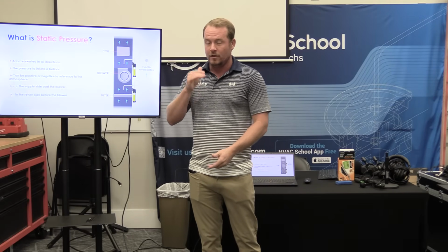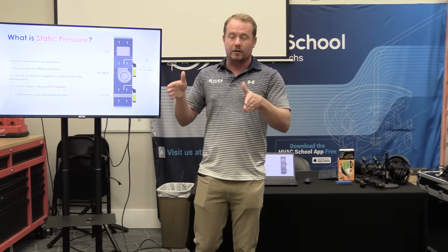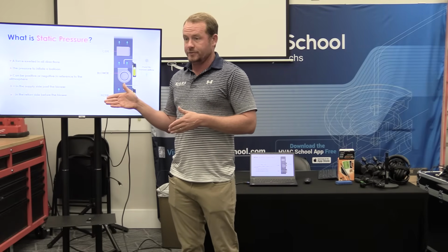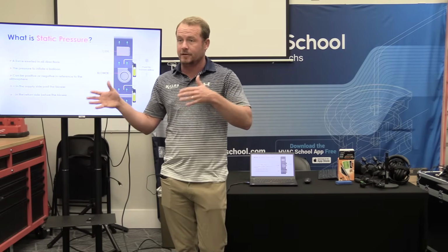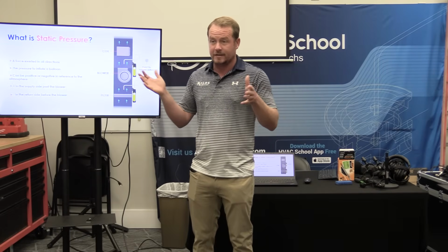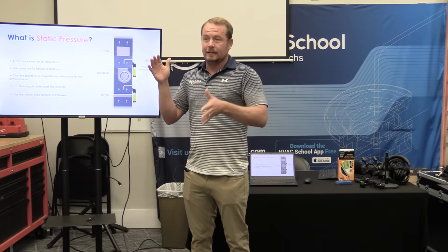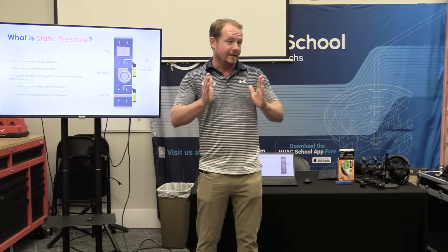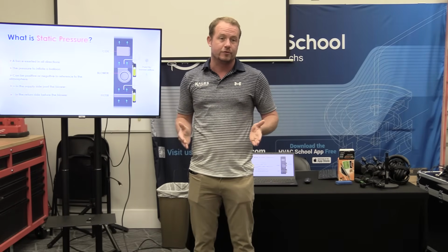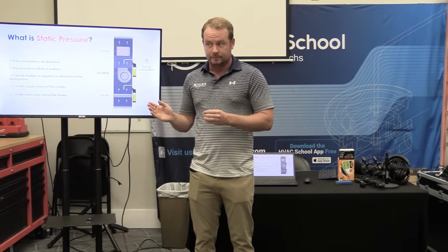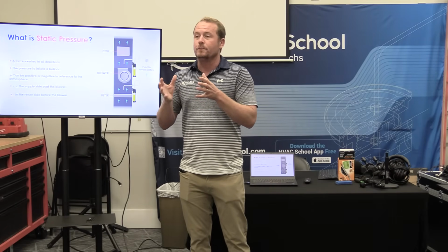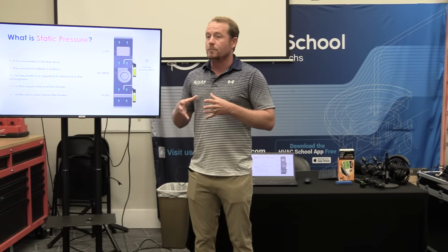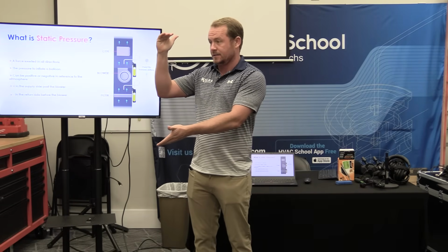They know everything about the coil. When you take a gas furnace and you stack a coil on top of it, the manufacturer may make the coil, but they don't know what coil you're going to choose. In many cases, there are different coil types that could match with that furnace, in almost every case. So they don't know exactly what the pressure drop is going to be, so when they give you a static pressure rating on the furnace, that static pressure rating does not include the pressure drop across the coil. Does that make sense? So how do you measure static pressure in order to see whether or not you're at the rating of the equipment? You measure what's across what's in the box.